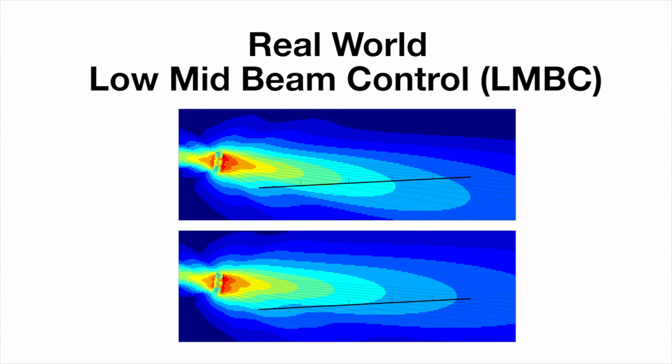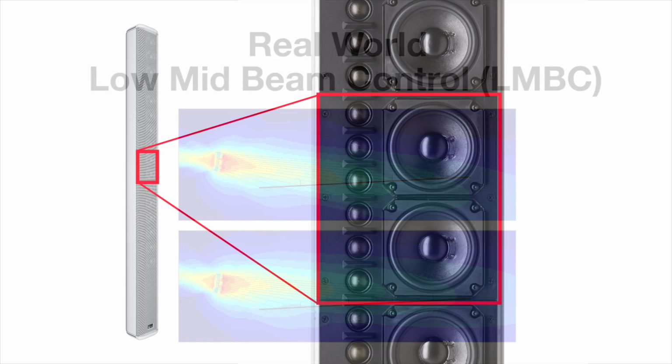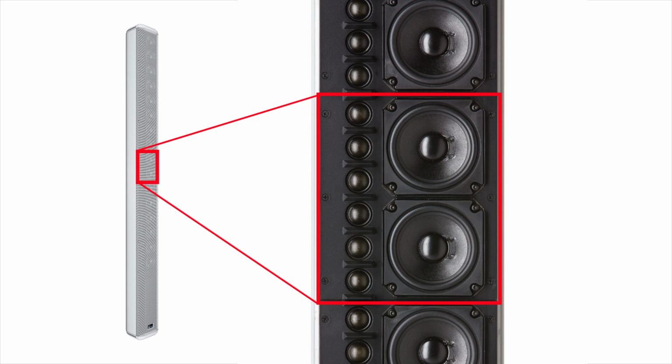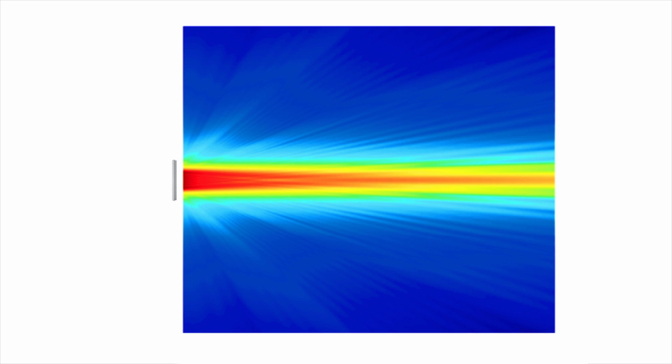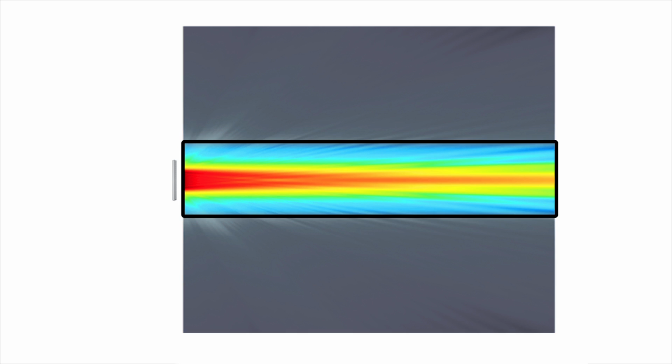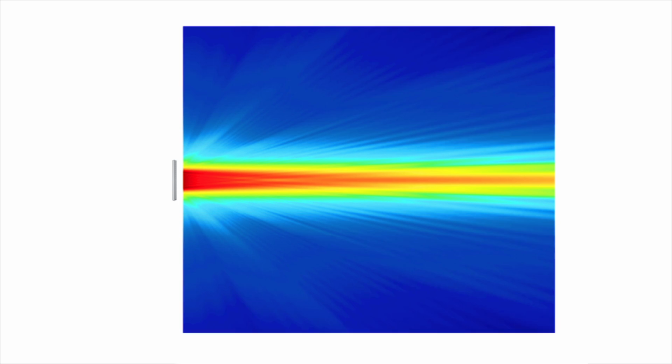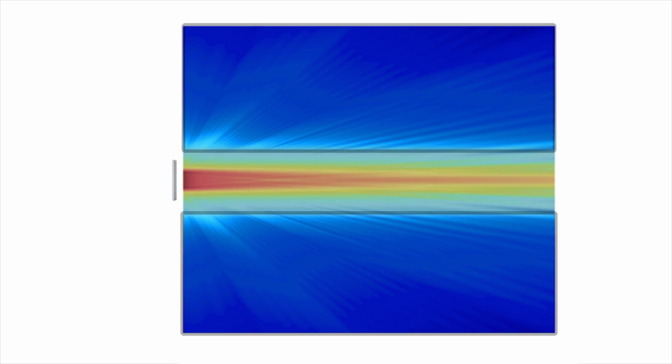Beam control can be achieved using different methods. Some are physical, and others involve signal processing. Loudspeakers without manifolds or horns rely on directivity control by committee, or phase steering. At locations where the acoustic output of each individual element arrives in time relative to the others, they add. When the acoustic output relative to the others arrives enough out of time, there's cancellation.